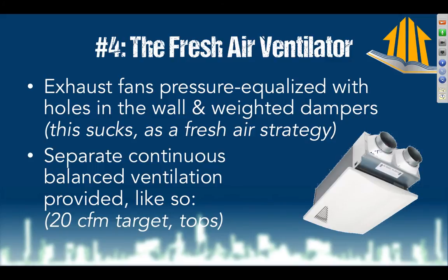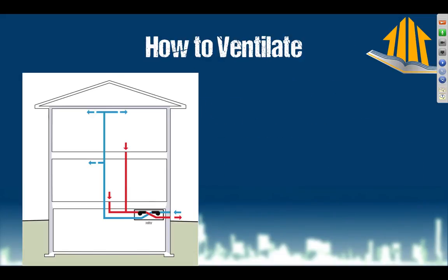Lou mentioned to me that if you were to provide 6 CFM to your nostrils directly, that would be a lot. That would probably be too much fresh air. So remember that we're talking about a very, very small place, and you want to use commensurately small and reasonable approaches. So this thing over here is an in and an out spot ERV, which I really like, and we're going to see about whether that's going to be what strategy exactly we're going to use here.